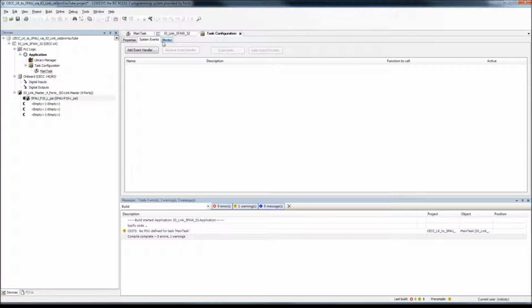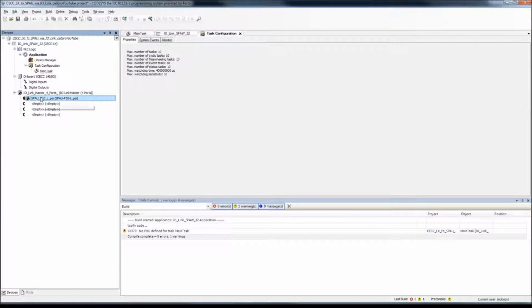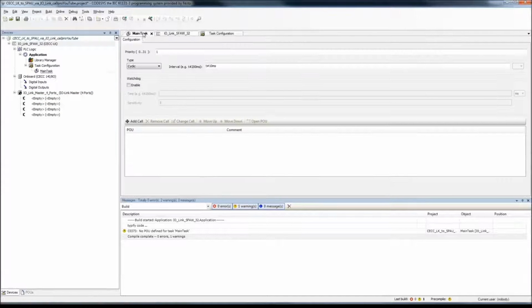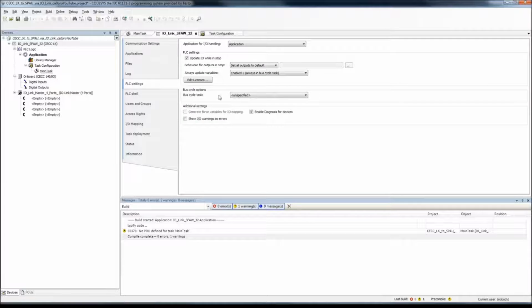So now we've got that in here. That's one way of doing it. I'm going to delete that, hitting the delete button, and I'm going to do another thing here. So in the sensor here, I always put on update IO and stop, and always enable. This is the Service Pack 7 CoDeSys project, so 3.5 Service Pack 7 Patch 2, I think it is.